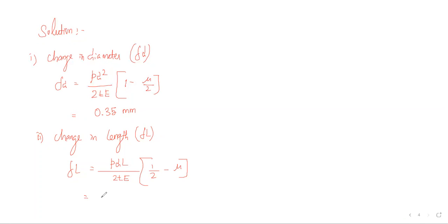If I substitute this, 2.5 into D into L divided by 2 into thickness into E multiplied with 0.5 minus mu. So it becomes 0.375 mm.